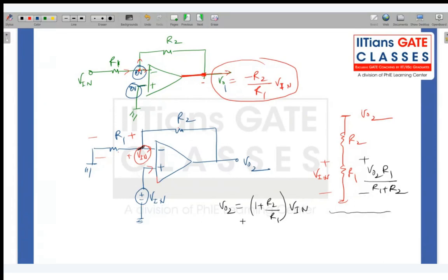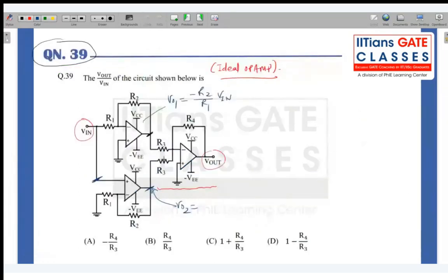Now let's get back to the circuit. As you can see, both inputs are connected at the negative terminal of the op-amp, right? Two inputs are connected, one is this, one is this. So you can consider this an adder circuit. These kinds of operations are why we call it an operational amplifier. These are the linear operations we do using an op-amp. This is an adder circuit because we are adding two inputs at the same terminal.